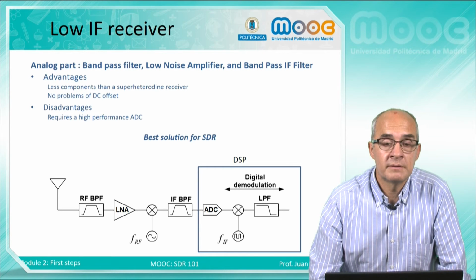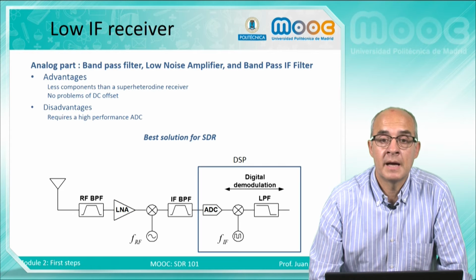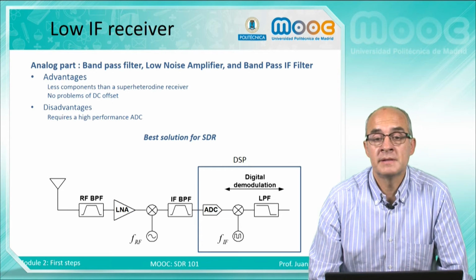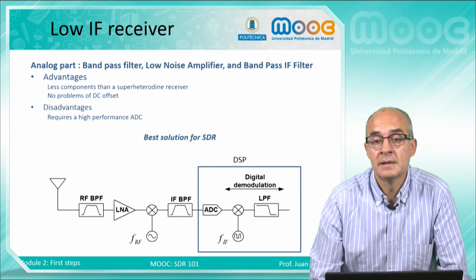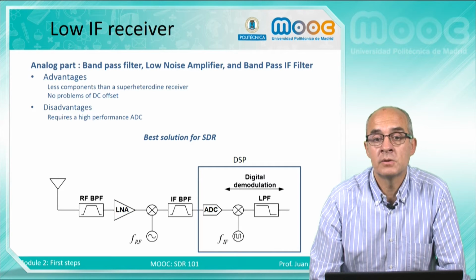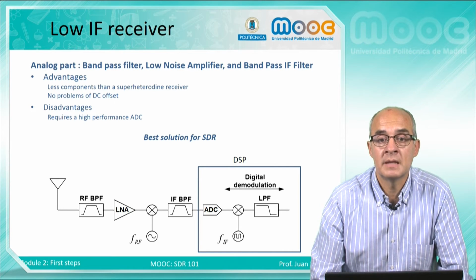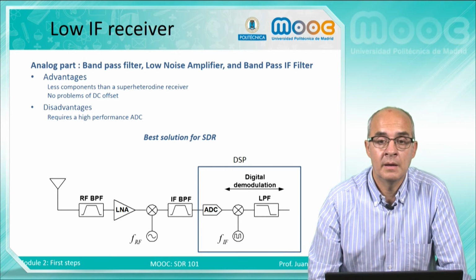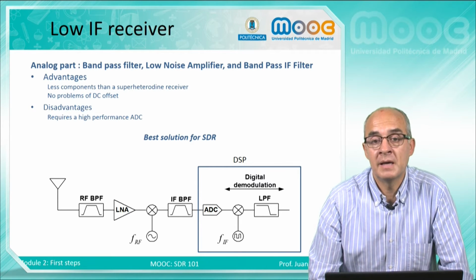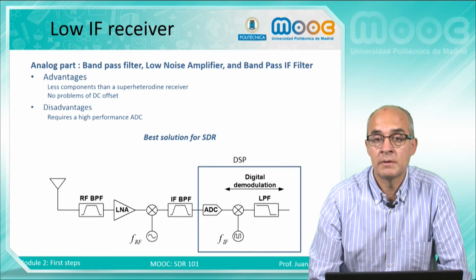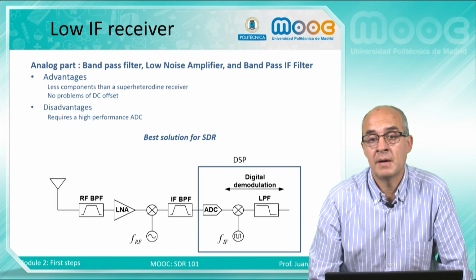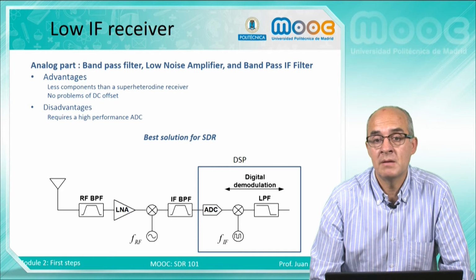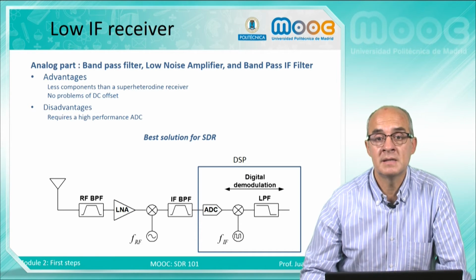Really, this receiver behaves like a super heterodyne receiver because it has the second frequency conversion made in a digital demodulation unit. This unit is included in the device and does the same things as the analog circuit in the heterodyne receiver, but digitally, so it can be integrated in a digital signal processor.